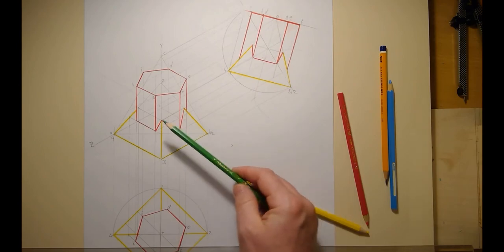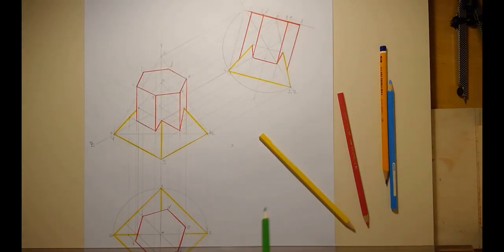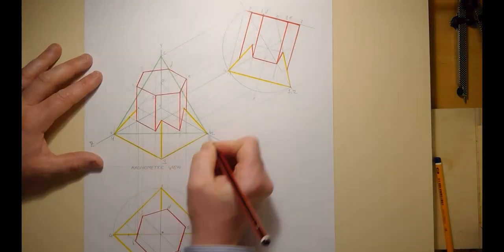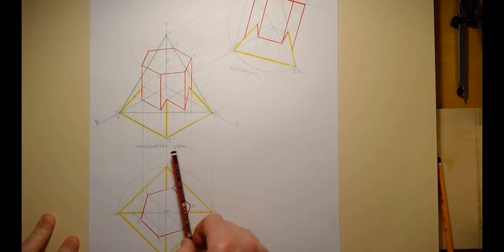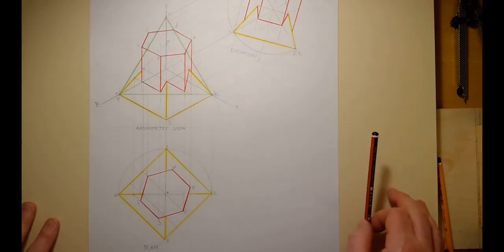To finish off my question, I would always make sure that my triangle and my axonometric axis are clearly visible. So I'm just going to put them in a bit of colour as well, as they do inside the question. Just a very sharp, light colour in pencil, and heavy with that. Always finish off your drawing. Label your elevation, going in the same direction of elevation, your axonometric view, and then down the bottom I also label up my plan.